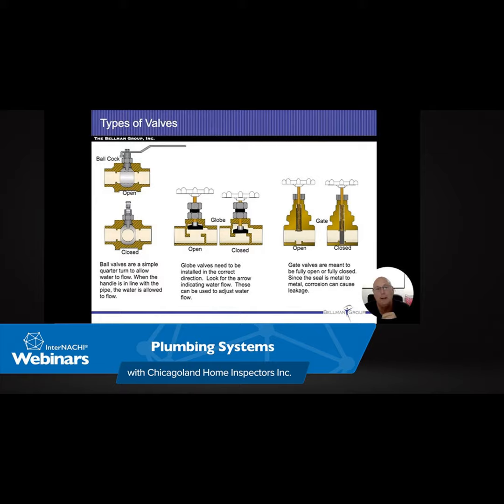They do have anti-siphon devices that you can install in the water system itself. All right, so it's not necessarily the end of the world. So when everything's running and pressurized, that cap in the right picture is pushed upwards, and that keeps the water from escaping. However, if I create a negative pressure inside the pipe, so now everything's going backwards in that pipe, that seals it up, opens it up, and allows air to enter. This way, air is going to enter the pipe, and we're not going to have to worry about any of that wastewater going into our drinking water.